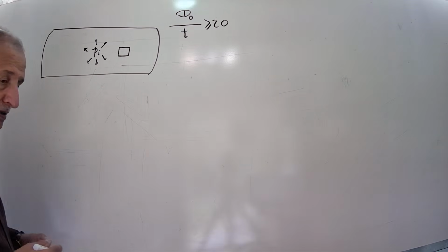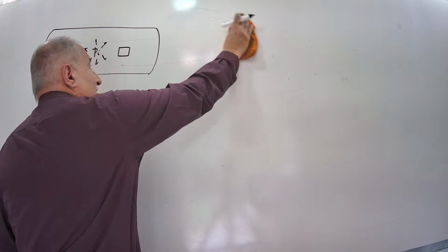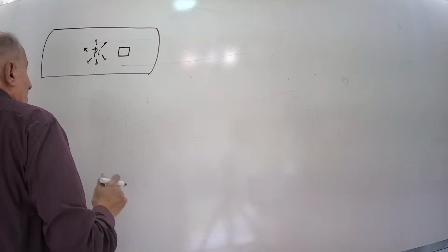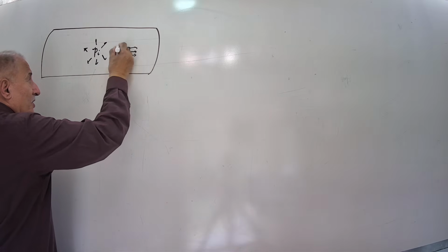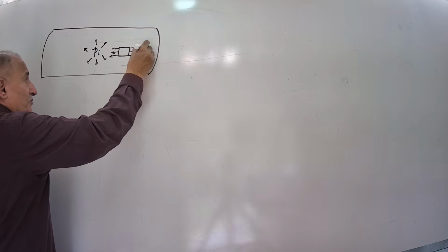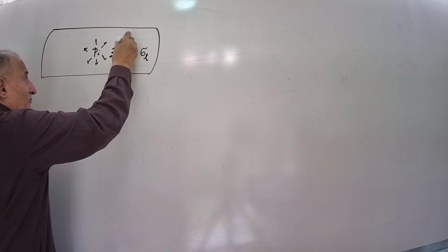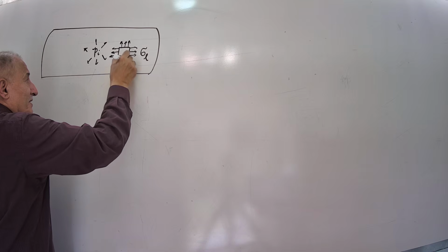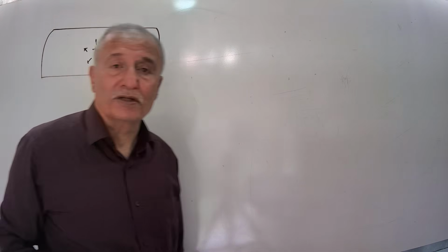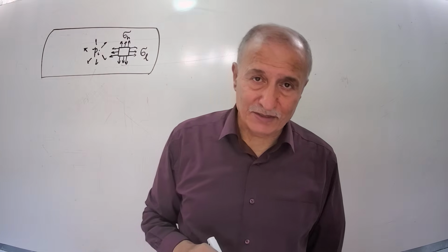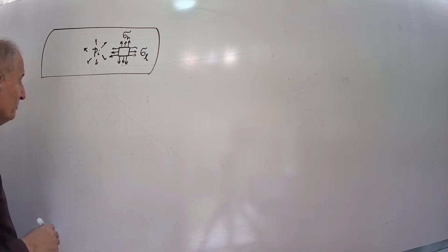Okay, this pressure vessel is thin, and we have only stresses in the longitudinal direction, which we call sigma longitudinal, and circumferential stresses, which we call hoop stress. Another name is tangential stress. Then we want to calculate them.